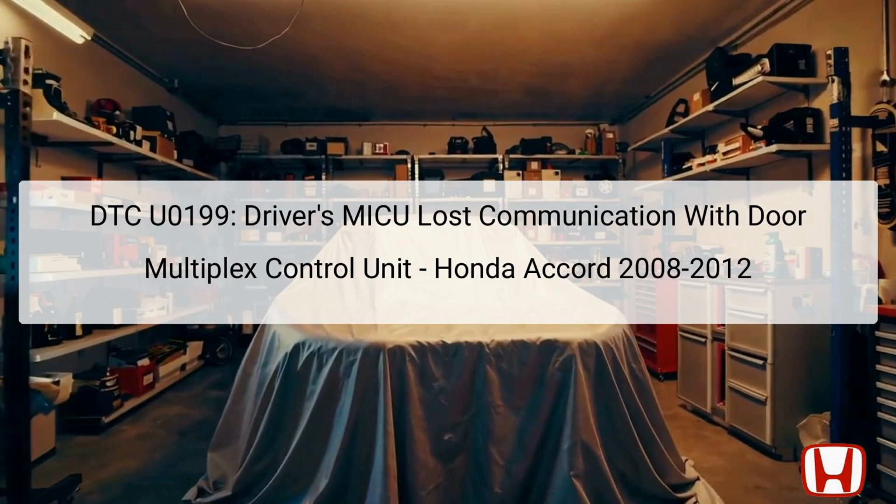The diagnostic trouble code DTC U0199 indicates a communication issue between the driver's microcomputer underhood interface MICU and the Door Multiplex Control Unit. The MICU is a central module responsible for various electrical operations, while the Door Multiplex Control Unit manages the power windows and door locks. The loss of communication can lead to several malfunctions, preventing normal operation of windows and locks.